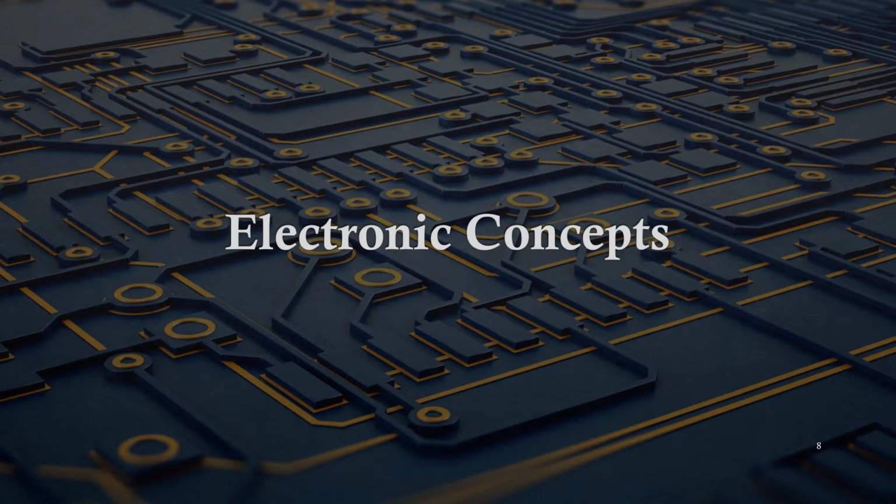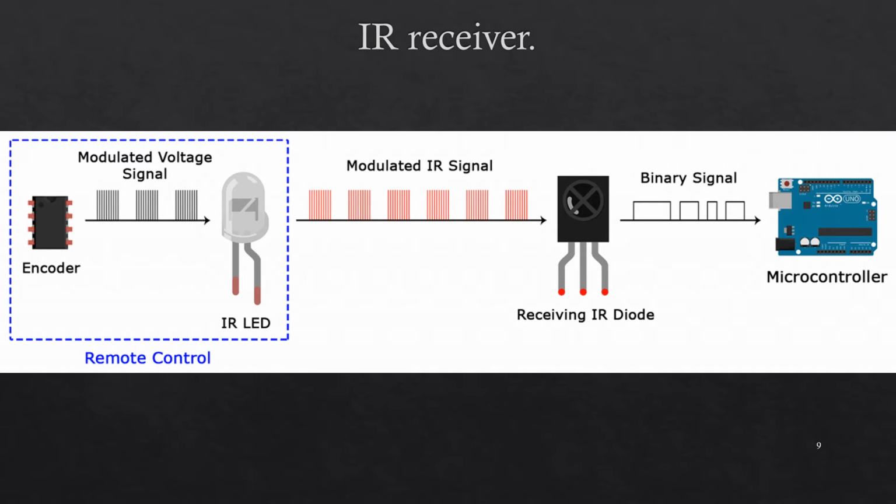In this section, we will only talk about the IR receiver. When you press a button using your remote control, the encoder in your remote control will encode the signal of that button to be a modulated voltage signal, and then it will be sent to the IR LED. The IR LED at the end of your remote control will then flash at a certain frequency, which will be the modulated IR signal, and it will be sent to the receiver IR diode.